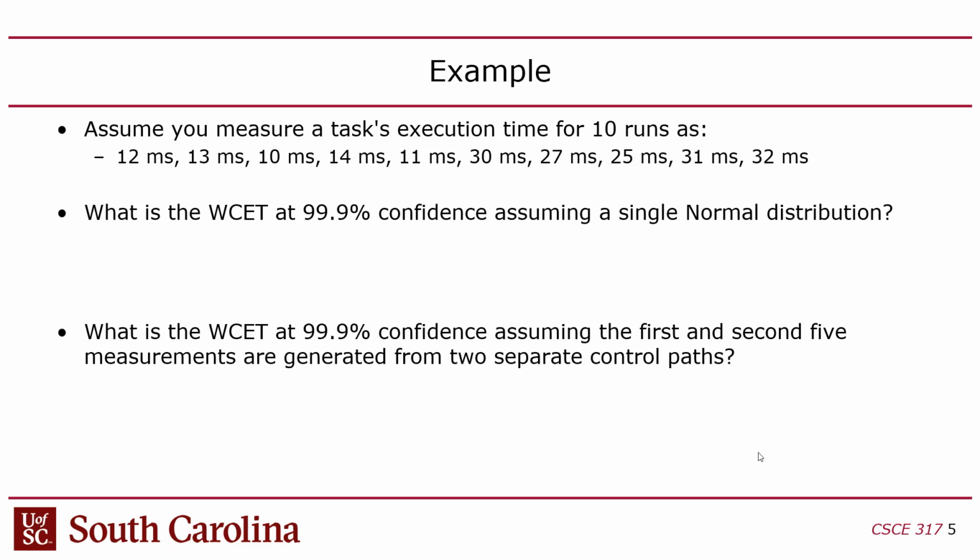There's really only one way to get zero variability of execution time, and that's an FPGA, basically. You have to put your design on an FPGA, and the FPGA can't have things in it like DRAM controllers and on-chip networks, network on chips. All those kinds of things can still introduce this uncertainty.